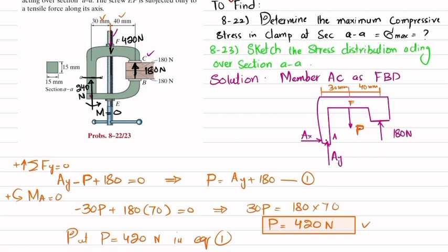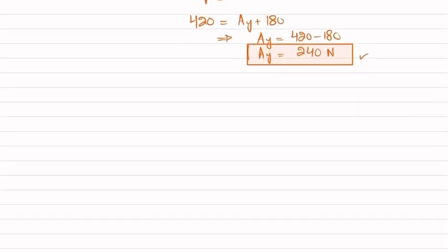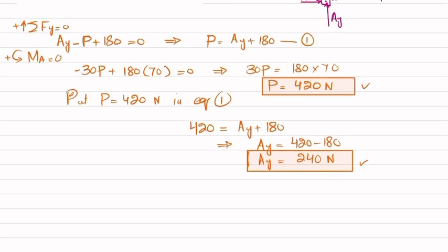You can also check how, because the sum of all moments about this point F will be equal to 0. So you can see that 180 multiplied by 40, that is counterclockwise, will be equal to 240 into 30, and the net moment will be equal to 0.